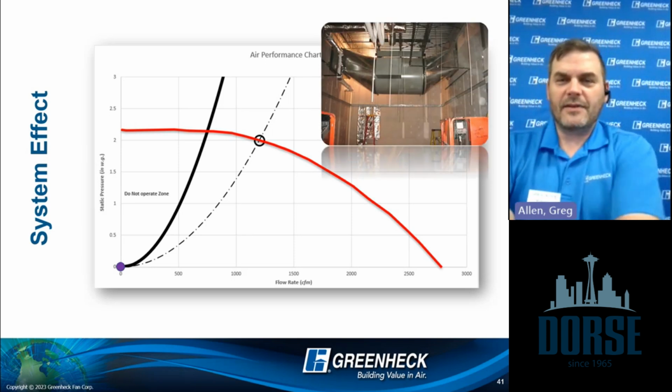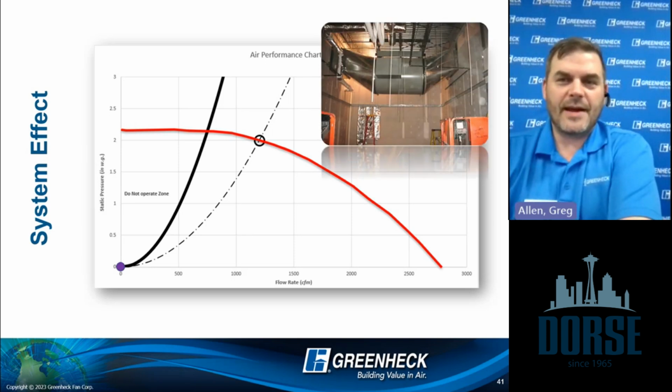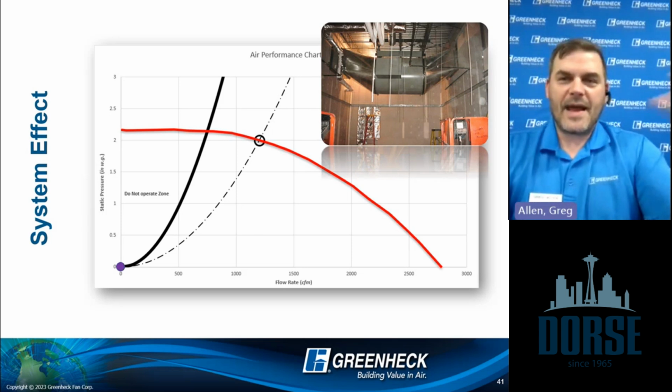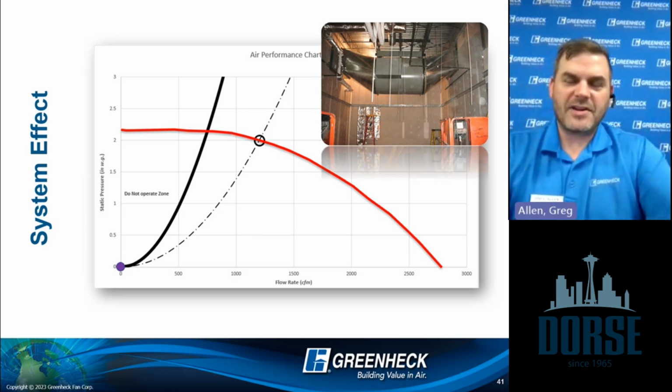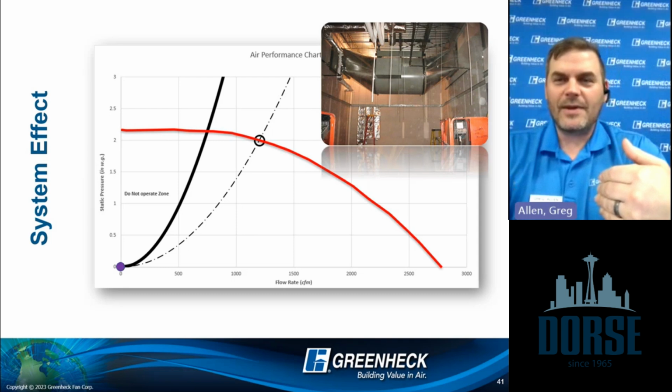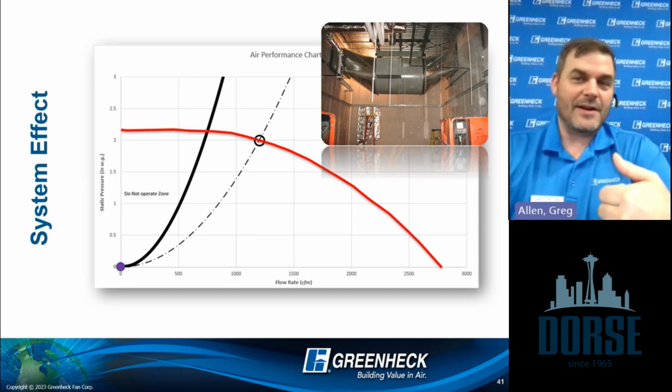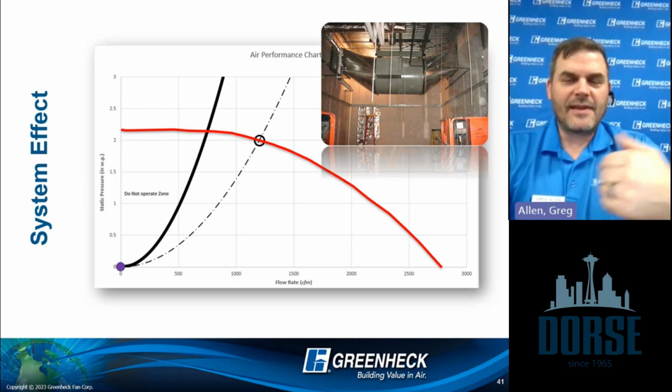But this is my installation we're going to have today, right? I have this fan where I am actually expanding and coming in at an angle. And then on the outlet, I'm restricting and at another angle. That does not look like how I tested this fan.